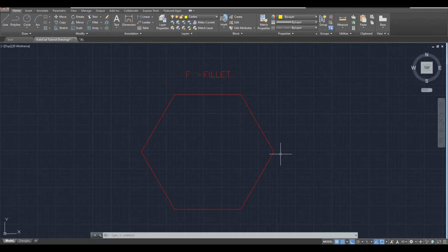So if you're working with a fillet, you have to consider the size or the scale. So basically I'm going to create an easy fillet right here of a radius of maybe say 4 or 5 millimeters. Let's work with 4. So I'm going to go ahead and make sure my command bar is selected, or my command line. I'm going to hit F, enter, and then it is going to ask me to either type in the radius.